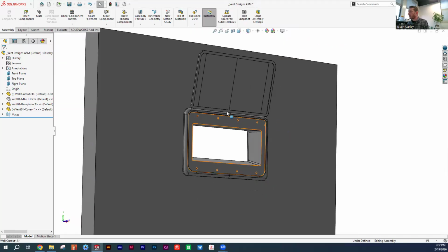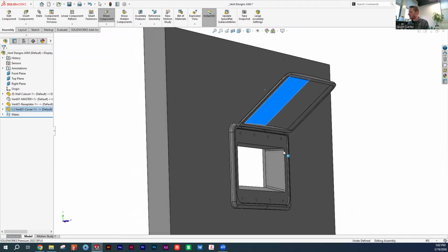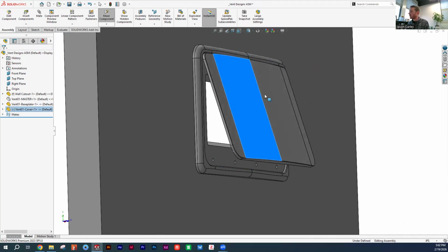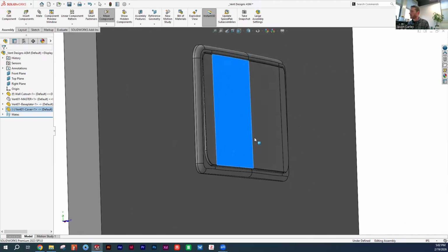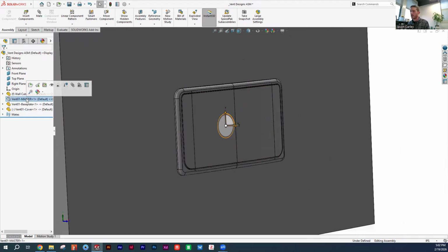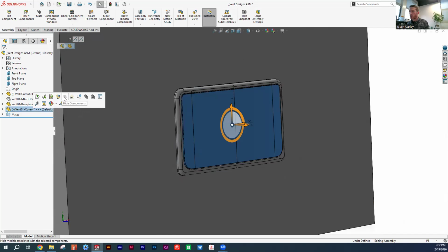All right, so this is the CAD model that I used for our demo that we had in class. As you can see, I've got our product with a moving door on here. Both of these parts came from the same part file that I used and called a master, which is here in the assembly. I just have it hidden for easy reference, so I can pull that up and make edits as I need to. I also have derived parts that come from that master part that are positioned in the assembly. So I'll show you how I do that.